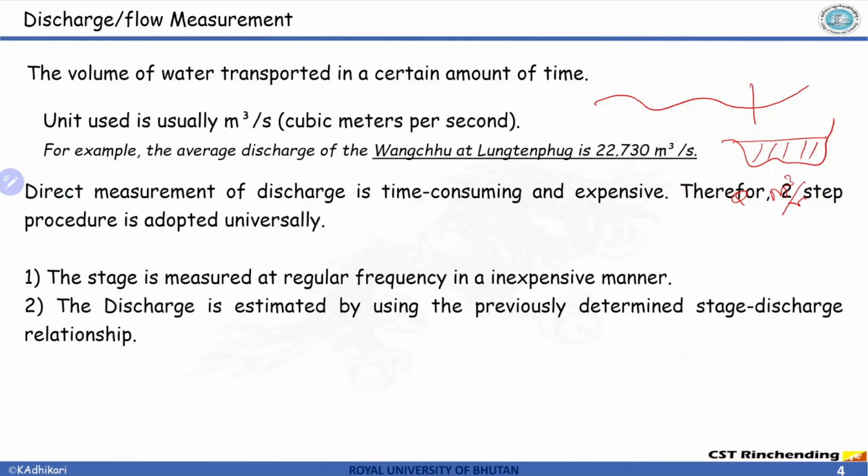And the volume time method, whereby you will be recording volume, is only possible for a very small stream. If you are talking about a river, then it is not possible, because you cannot store that much water in some bucket, right? So it's impossible to do that method. So we usually use direct or indirect methods. So in this chapter we'll be focusing on the area velocity method.